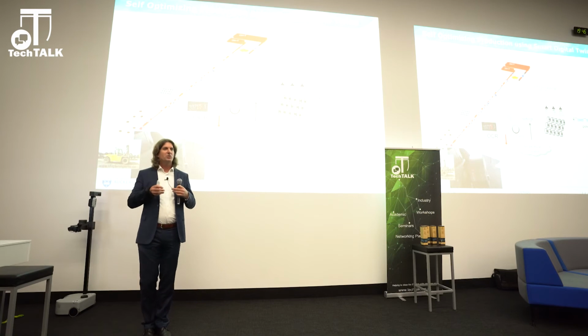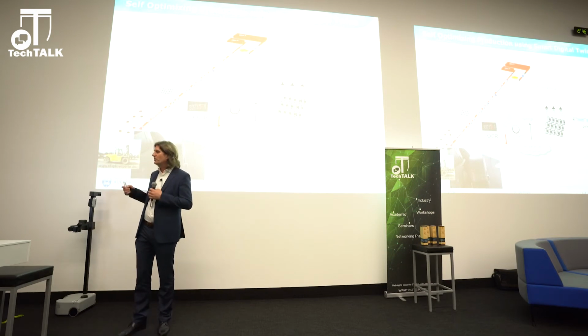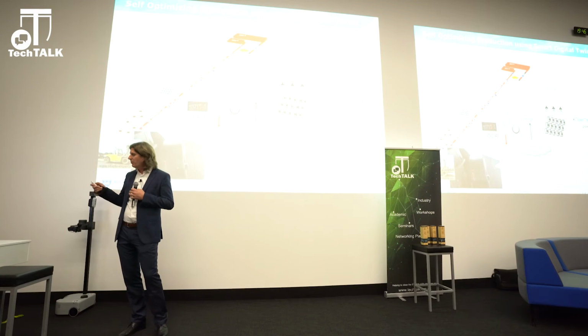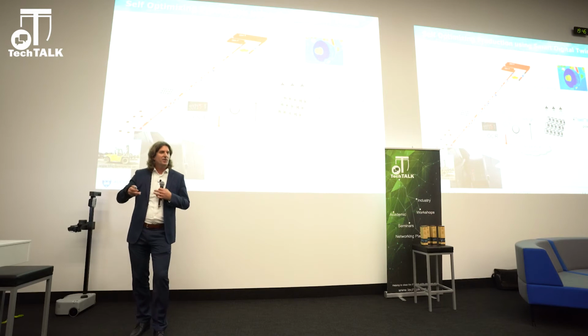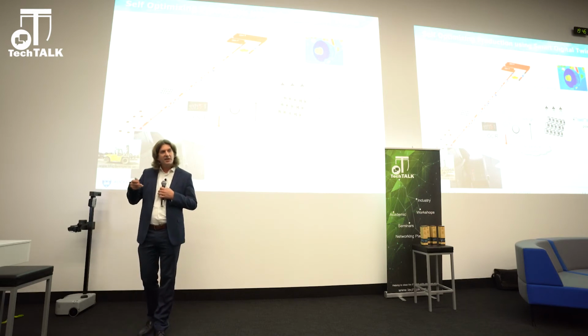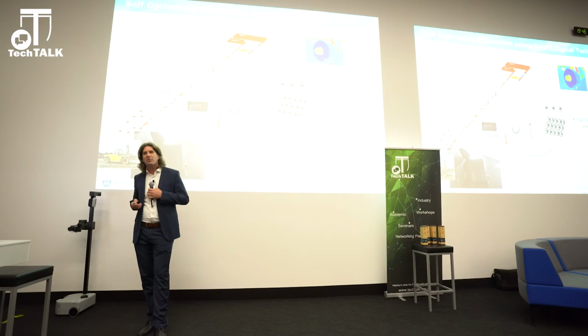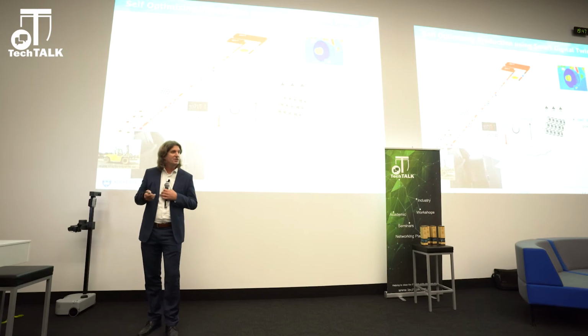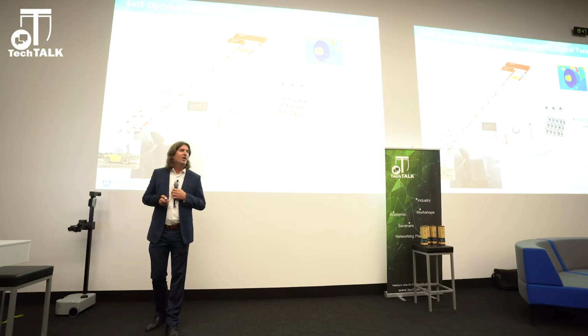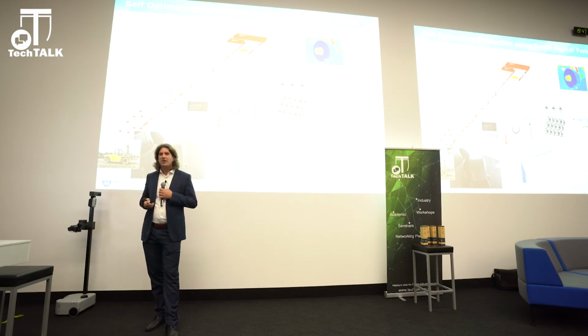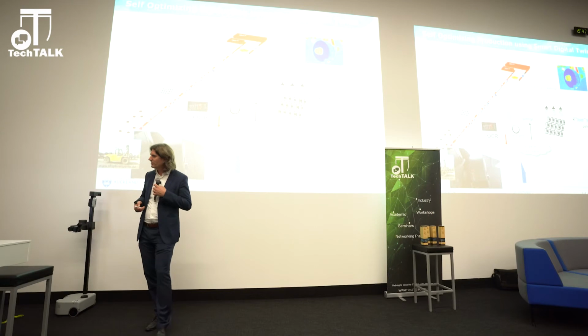The reason why we introduced that virtual copy is that the coil itself is dumb. It can't do any communication and any optimization. So that digital twin starts a communication with the pickling line. There's also a digital twin running, and it asks, when are you going to process me? It's got also models inside doing a calculation that in 18 hours I would like to process you. Our digital twin now says, okay, at the moment I've got 650 degrees, and in 18 hours I would like to have maximum 80 degrees, but close to that. It looks outside at the temperature sensor, we've got 10 degrees. We've got some feedback here all the time.